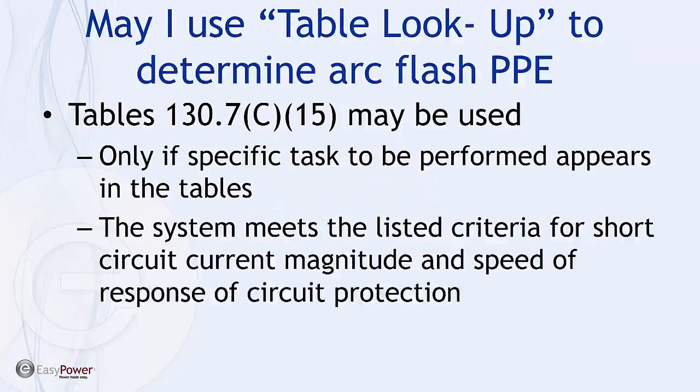May I use the table lookup to determine arc flash PPE? Again, an area that's been in NFPA 70E discussion for several iterations, and as of 2015, there's been more specific direction in this regard. The answer is yes. Tables 130.7(C)(15) specifically, and (16) may be used only if the specific tasks to be performed actually appear in the tables, and the system meets the listed criteria for the short circuit magnitude and speed of the response of